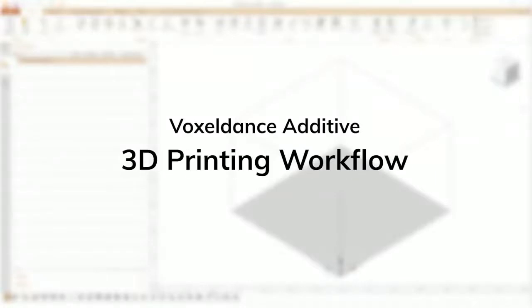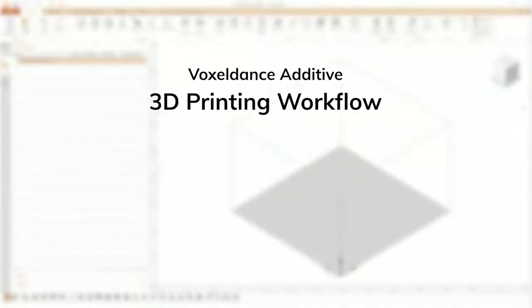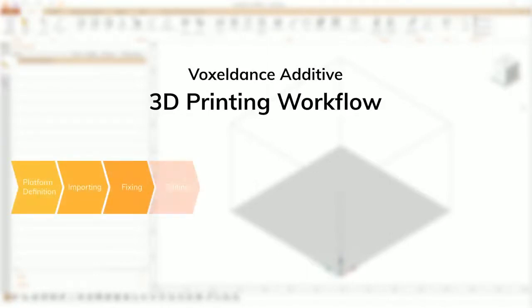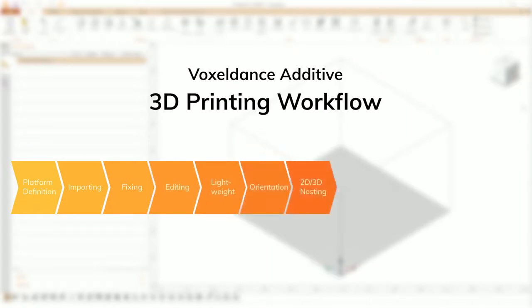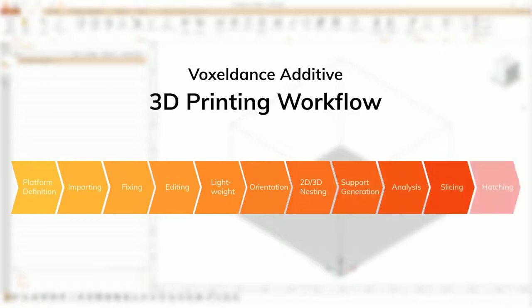A complete 3D printing workflow in Voxeldance Additive includes the following steps: platform definition, importing, fixing, editing, lightweight, orientation, 2D or 3D nesting, support generation, analysis, slicing, and hatching.